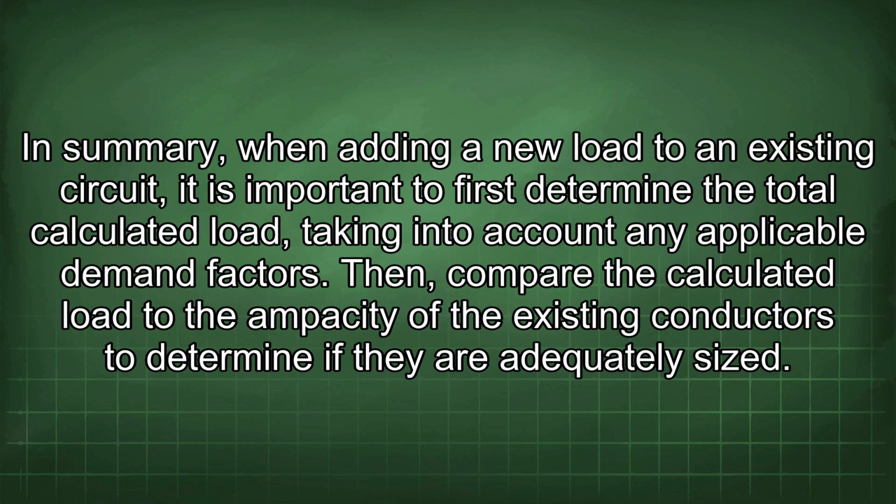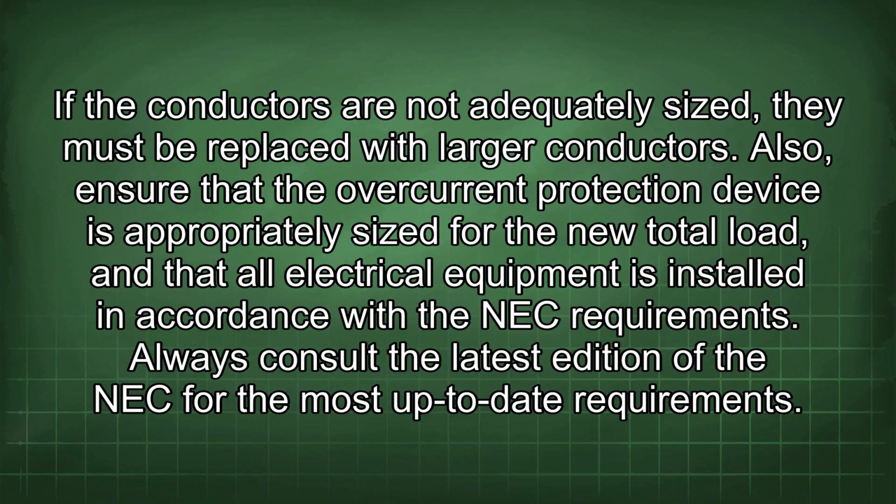In summary, when adding a new load to an existing circuit, it is important to first determine the total calculated load, taking into account any applicable demand factors. Then compare the calculated load to the ampacity of the existing conductors to determine if they are adequately sized. If the conductors are not adequately sized, they must be replaced with larger conductors. Also, ensure that the overcurrent protection device is appropriately sized for the new total load and that all electrical equipment is installed in accordance with the NEC requirements. Always consult the latest edition of the NEC for the most up-to-date requirements.